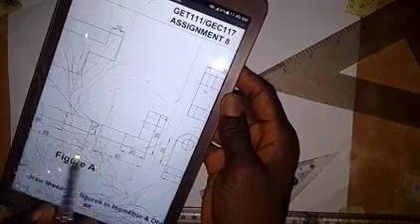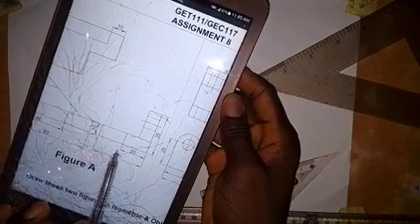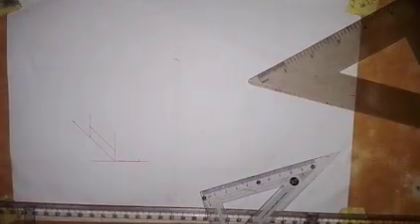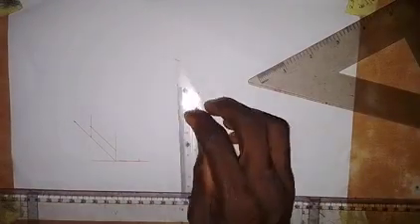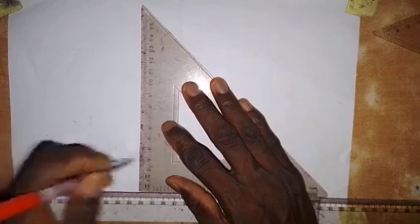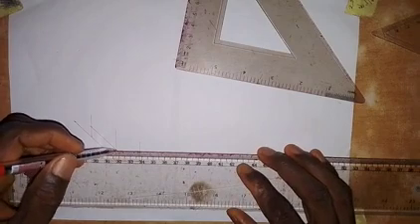In the end elevation, we have it as 20, that is from here to here. The balance from here to here, out of this 40, is also 20. So that's the measurement that I have taken. At this point here, we draw a vertical line, and then we transfer this 20 onto this line, like this. At the same time, from this point also we are going to draw a line at 45 degrees.